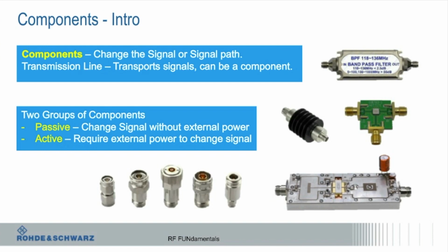In the end, most people are designing a transmitter, a receiver, or both, a transceiver. If you're designing a transceiver, there's all this stuff in there, so we'll just call that an active device. You may make similar measurements that you would make on each component, but for the whole system. Whatever you're making, if you're a component person, your component goes into a system, and that system has to work, right? So we look over a link budget. What's a transmitter supposed to look like? Can I transmit enough power that can be received at the other end with the right amount of power, and I can decode it and take my information out of it? In the end, that's what we care about.